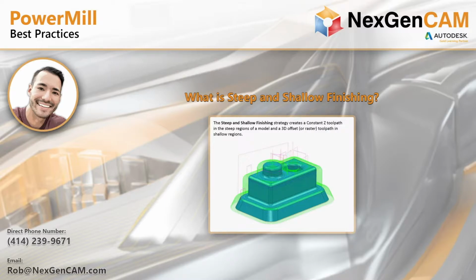Now, what is steep and shallow finishing? Steep and shallow finishing creates a constant Z toolpath in the steep regions. What we saw before, all those near vertical or vertical walls using a constant depth of cut, that was the constant Z toolpath. So it's going to utilize that toolpath on the steep regions of a model. And in the more shallow areas, it's going to be utilizing the 3D offset toolpath in shallow regions. So just remember that. And you do see that it does say or raster. In 3D offset, you can either do an offset setting in steep and shallow, or you can use 3D offset as 3D raster finishing. We'll get to that later on.